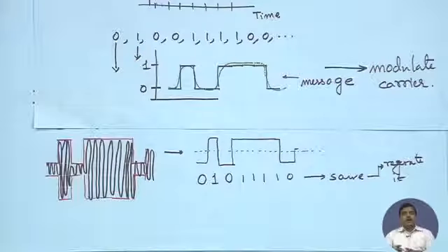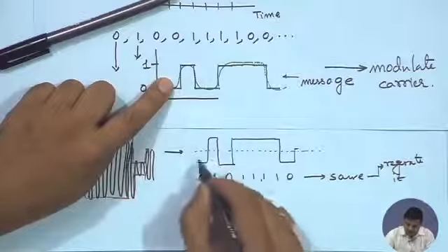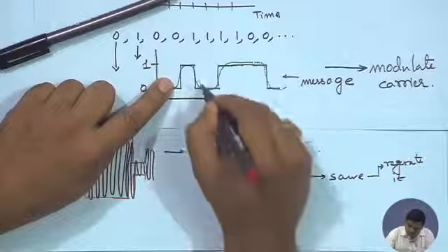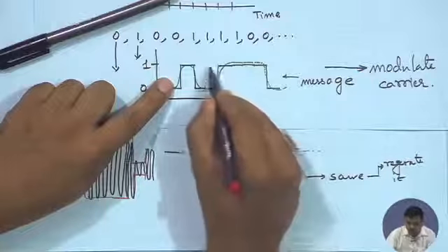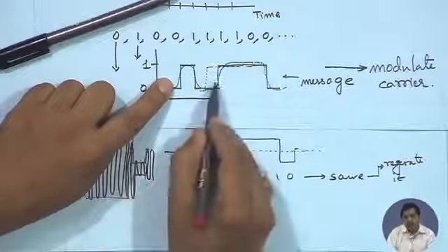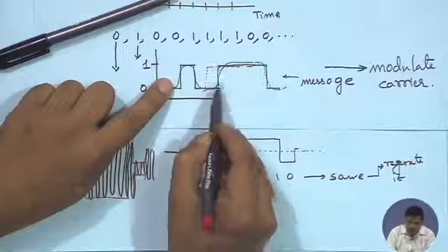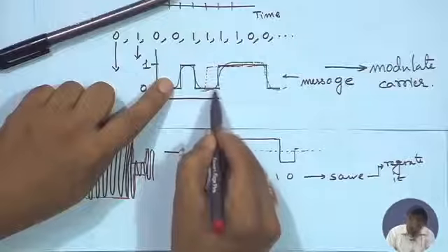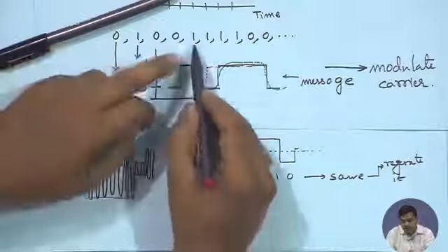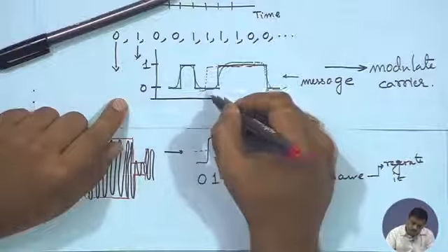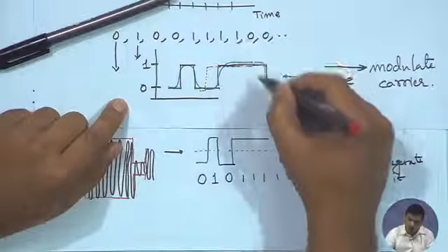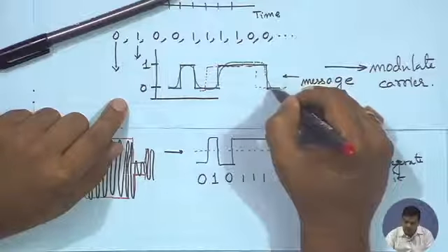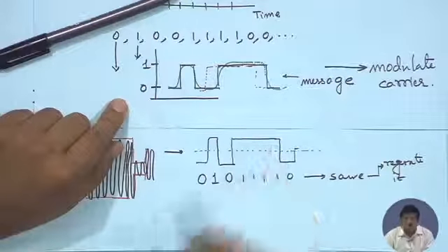If this was an analog communication system, this particular waveform that we have here is now received in a little bit different way. As if my 1 has started to be generated at this point instead of this point. So this 0 has been received as a 1, or sometimes we can say that we have missed out this particular 0 and instead we have read the next one. It is your interpretation, or you can say that 0 has become a 1 and one particular 1 has become a 0. So, as if the waveform has changed like this in this particular picture, right.